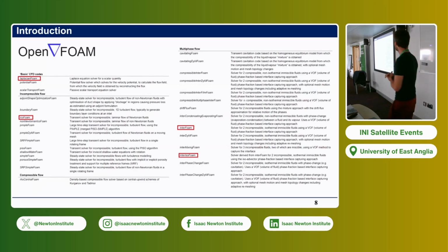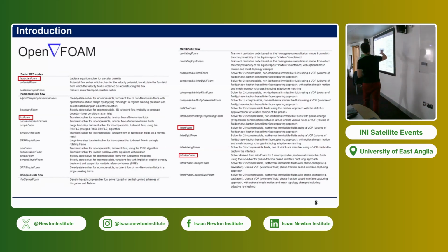And here is a probably not exhaustive list of all the solvers you have in this version of OpenFOAM, with a brief description of them. Now, today we will only use interFOAM and interisoFOAM. interFOAM is a multi-phase flow solver based on an algebraic volume of fluid method. Algebraic because it doesn't reconstruct the interface like, for example, Basilisk is doing.